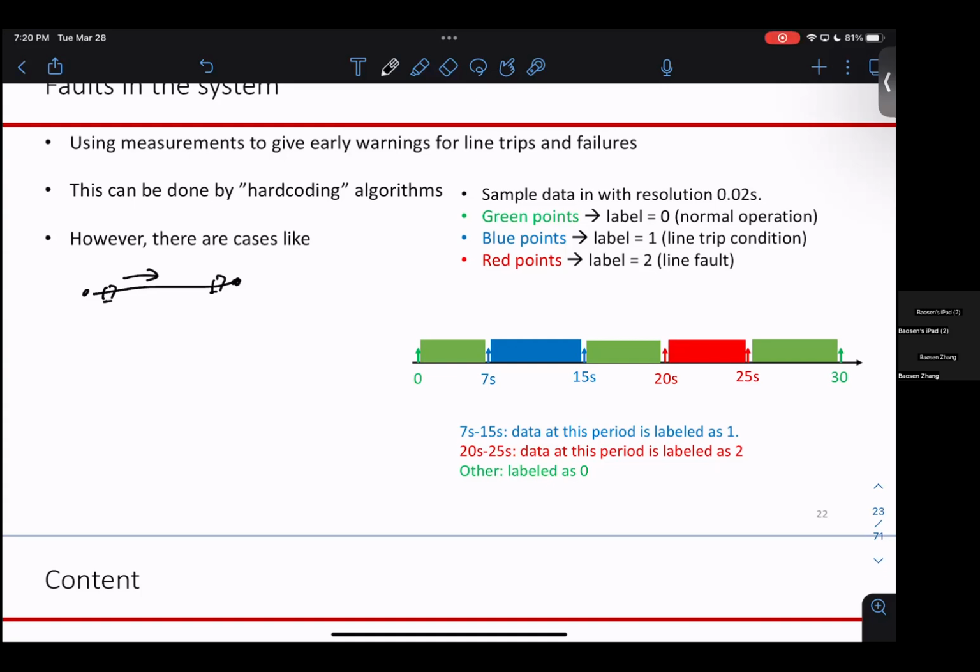So lightning strike can cause high current. A small animal getting here will cause high current. Again, it happens more than you think. But those again are sort of one-time events. So the way this thing works is if you measure high current, the line actually opens. Both sides will open if you measure high current.